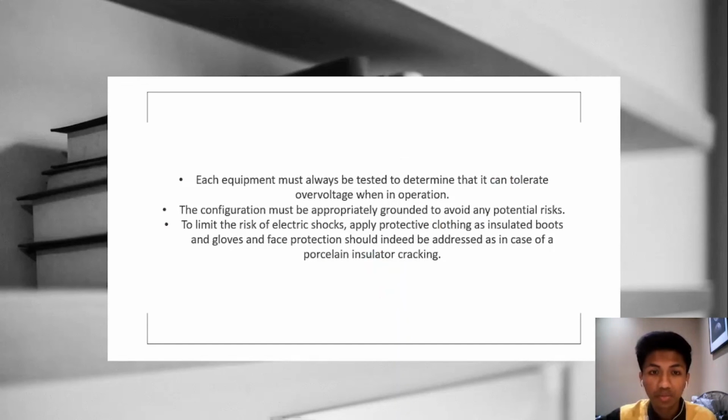Each equipment must always be tested to determine that it can tolerate overvoltage when in operation. The configuration must be appropriately grounded to avoid any potential risk. To limit the risk of electric shocks, apply protective clothing such as insulated boots and gloves, and face protection should indeed be addressed in case of a porcelain insulator cracking.